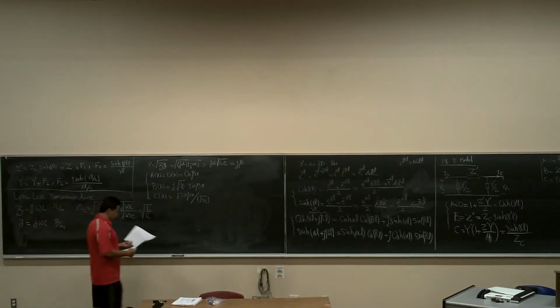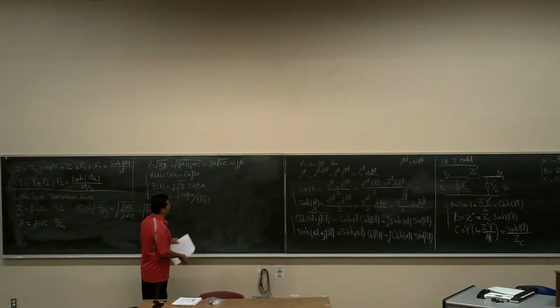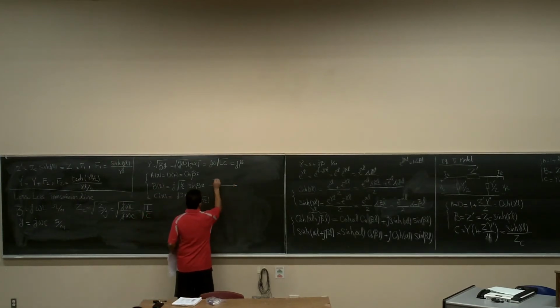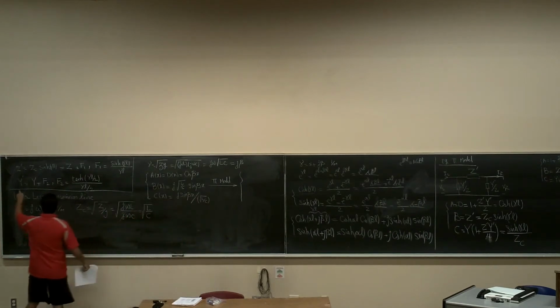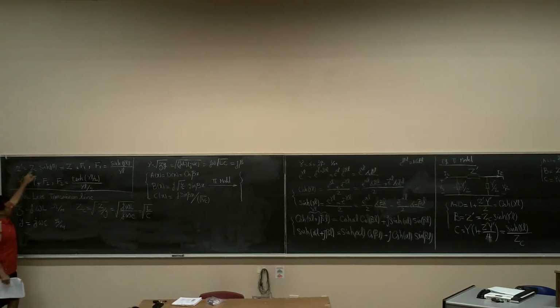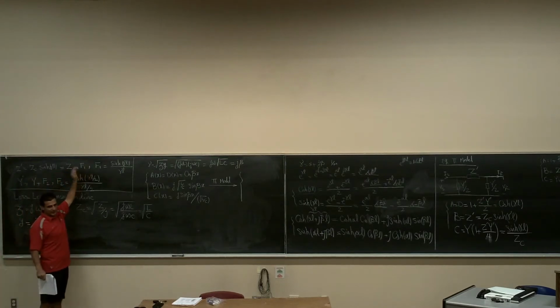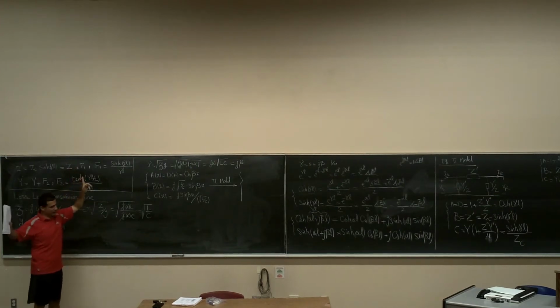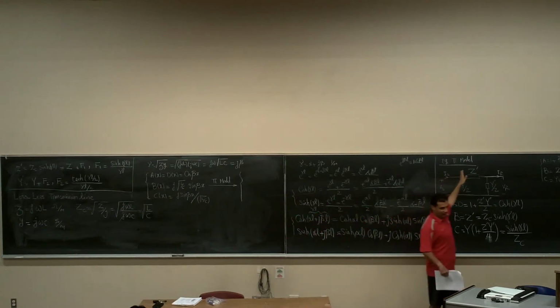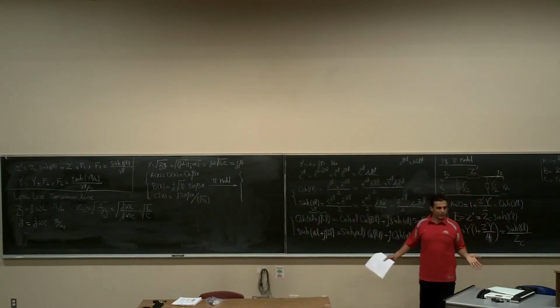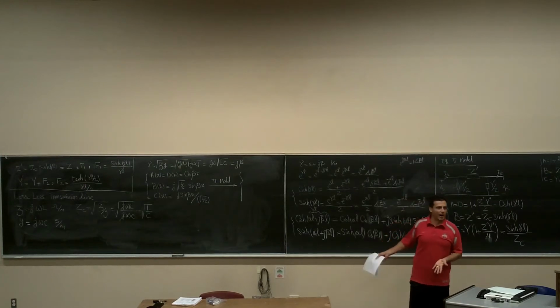Now, if we want to find the equivalent P-pi model, again, the way we did it here and we calculate over there. Look at here. How much was the Z prime? Z prime was Z times F1. In this case, only there is an X, because Z was the series impedance. Look at here, Z was this series impedance, so there is no R. So let's call it X prime.